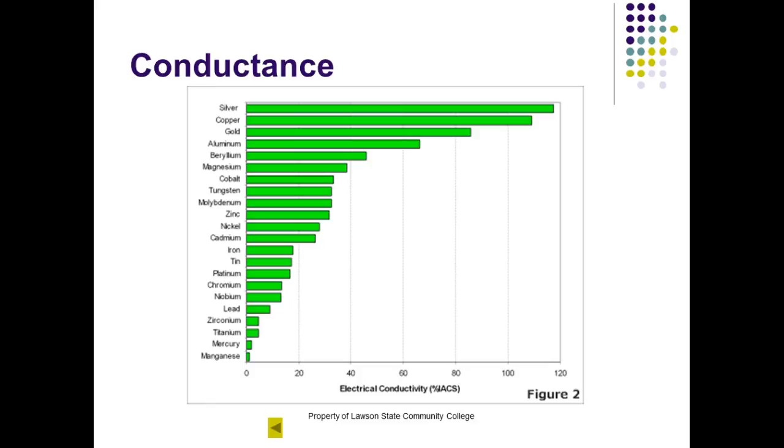By the way, aluminum and copper are dissimilar metals. The big problem we have with aluminum is it oxidizes real fast, which means it rusts real fast. Aluminum oxide is an insulator. The problem with mixing copper and aluminum is they're dissimilar metals, and when you mix dissimilar metals, they set up something called electrolysis and they will eat themselves up. So if you're going to mix copper and aluminum, there's a paste you buy. It's an antioxidant that you coat the aluminum wire real good with, and you can mix them all day long. Then make sure if it's outside that you tape it up real good.